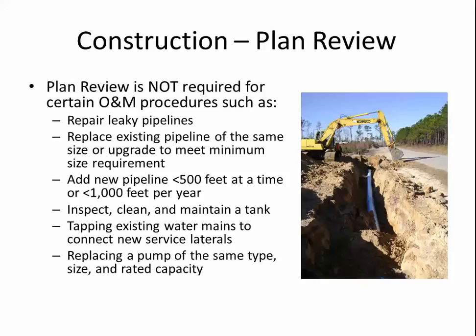Also, if you're inspecting, cleaning, or maintaining a tank, if you're tapping into existing water mains to connect to a new service lateral, or if you're just replacing a pump of the exact same type, size, and rated capacity, these items you would not need plan approval for. But I always say, if you have questions about whether or not you should get plan approval, just please call our main office and ask to speak with any of the engineers who might be available.